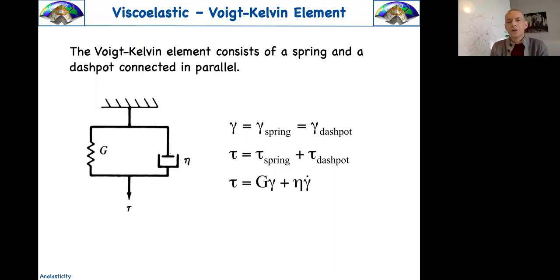Okay, let's call it the Kelvin-Voigt or Kelvin. Now let's consider a parallel. Now the stress is the sum of them, not the deformation. So its dynamic equation is this one. And now you can imagine putting this at an extreme. If that is going to be zero, again, that branch is not going to work. If it is infinite, well, nothing is going to work. You cannot move it.